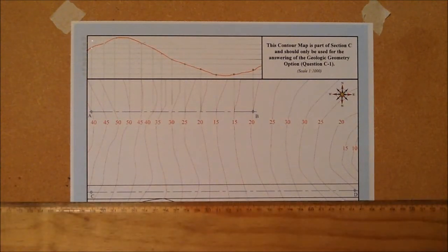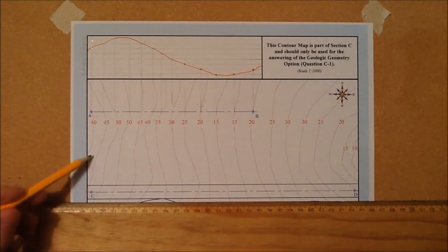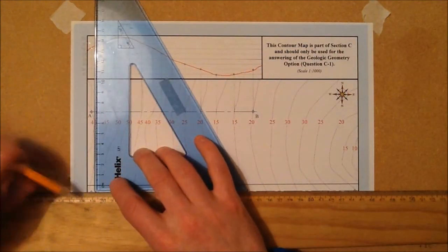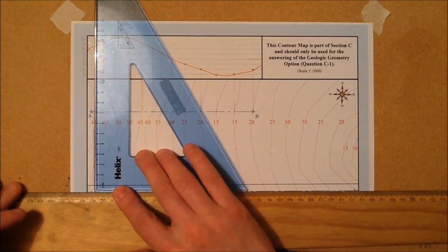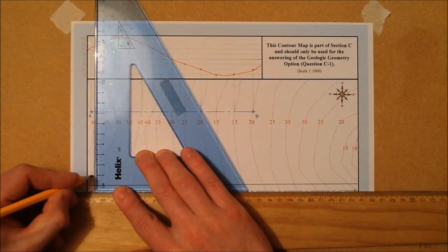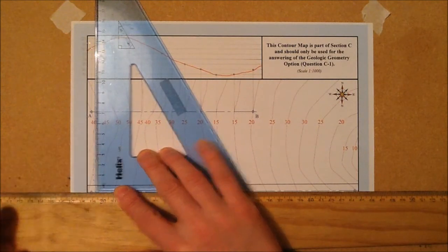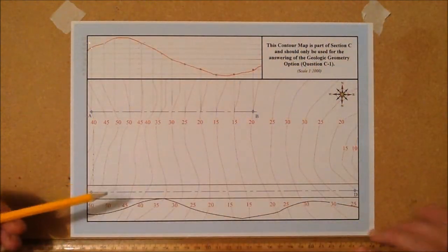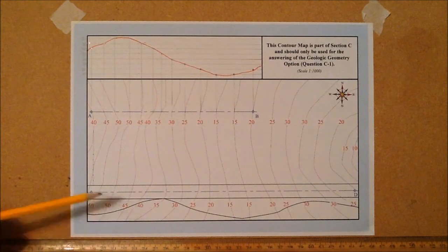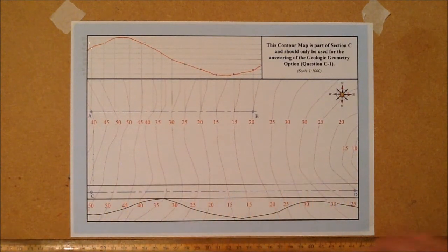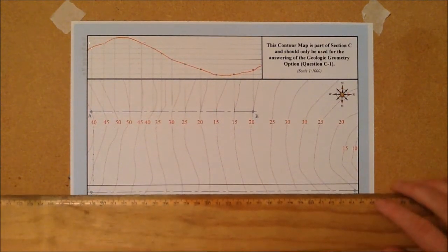Okay, again, like we did here with our profile, I'm going to first of all mark out my contours in position. Okay, so as we know they're 5 metre intervals, we will space them out just along here. I'm going to draw a vertical line from the road and I'm going to measure those 5 metre intervals. Again, these will be ranging from 15 metres up as far as 50 metres in altitude. So depending how much of a difference there is in the metres, that will tell you how many lines of altitude that you will need to put in.